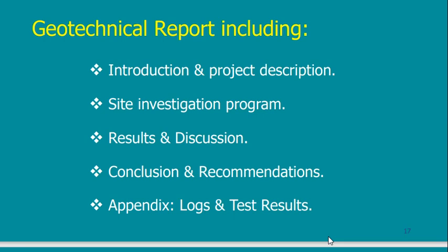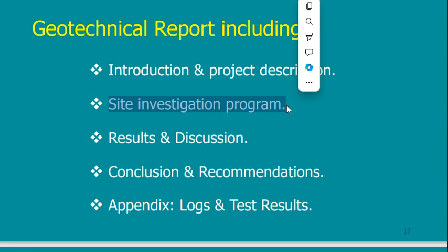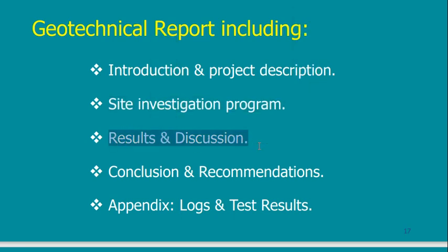Now you have done an investigation. You have the knowledge in your mind. How can you present it to other people so that they would know what you have done? Then you have to prepare a report. This report will include what? As a minimum, introduction and project description, of course. If I need to tell the people who are going to read this, what is this document containing? Then I will tell them my site investigation problem. What did I do? Boreholes, test pits, ultrasound, seismic testing, logging, what is the results, everything I have to put it here.